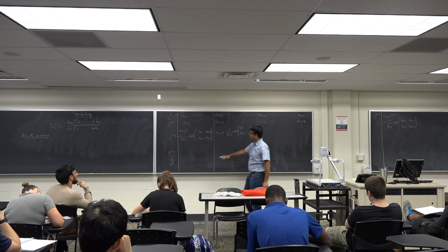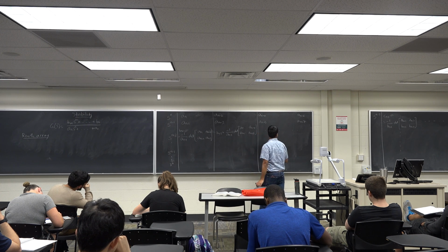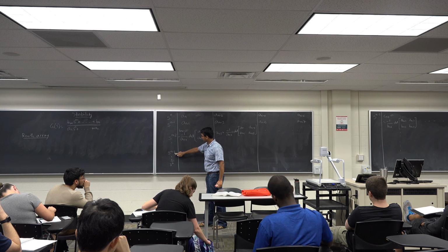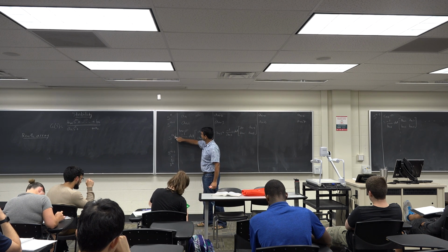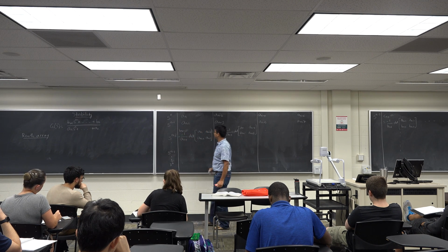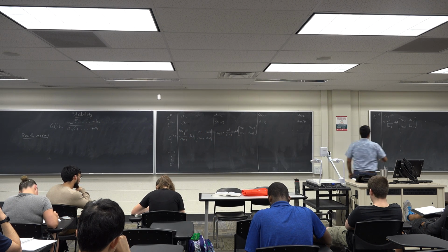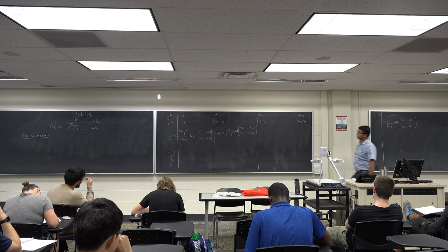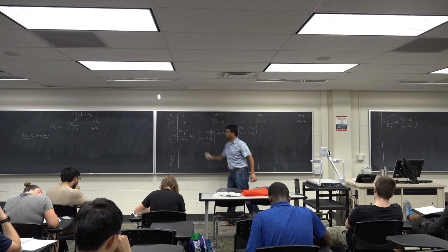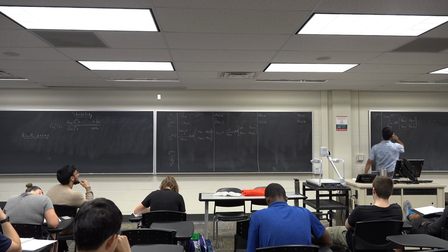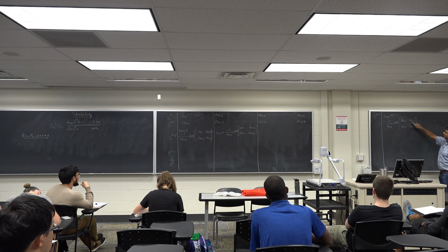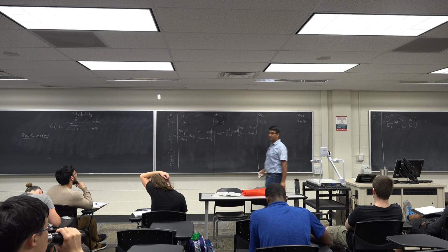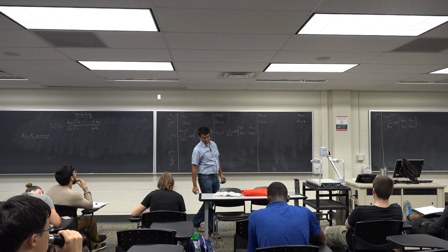Now when I get to Sn minus 3, I have to look at these two rows. When I'm constructing the Routh array for Sn minus 3, I have to look at the coefficients of Sn minus 2 and Sn minus 1. So I do the same thing again: minus 1 over Bn minus 1, which is this number here, and then the determinant of an minus 1, Bn minus 1 and an minus 3, Bn minus 3. I'm going to continue doing this over and over again.